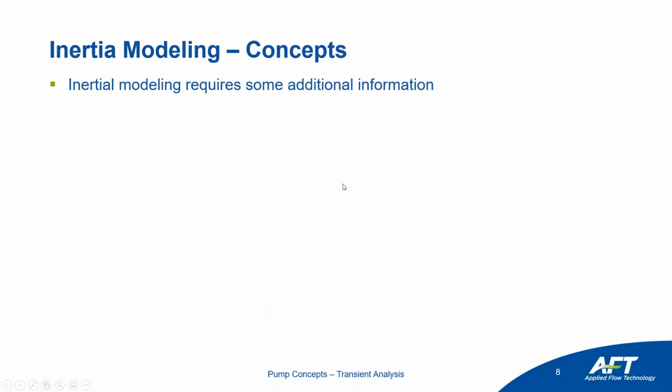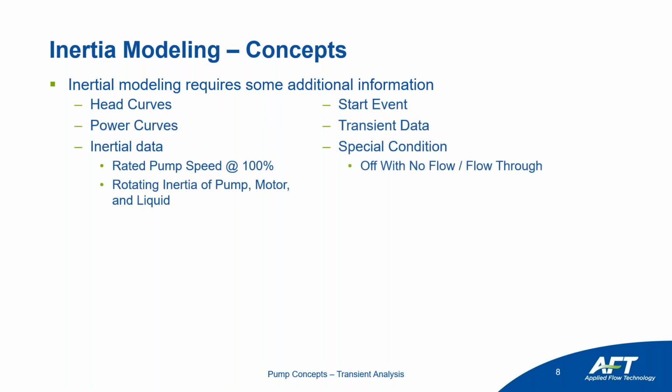So some of the concepts with inertia modeling, it's one of the more complex topics, is it does require some additional information. So it'll require things like the head curve, the power curves, inertial data, so things like the rated pump speed and that total rotating inertia, a starting event, transient data, and then special conditions. A lot of these you should already have if you're modeling a physical system,